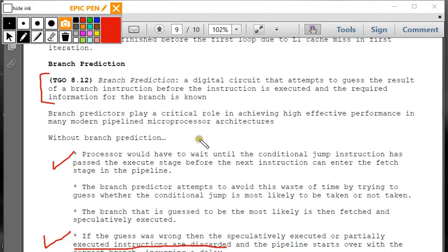So think about it with registers. You have registers that have the updated values, right? That's what we've done so far. That's what you're working on in your projects. So you actually have another set of registers if you're in the middle of a predicted branch, where you're doing your updated values and you store your original values. And if you find out that your prediction was incorrect, well, you just put the old values back in.